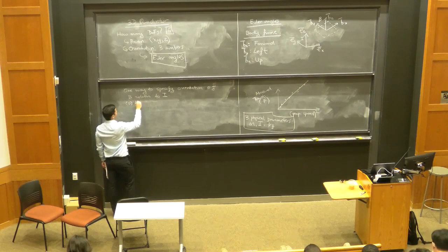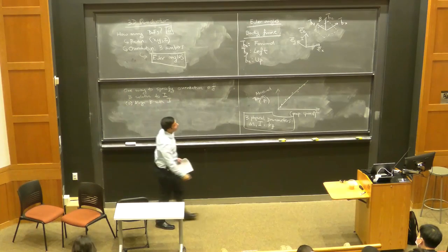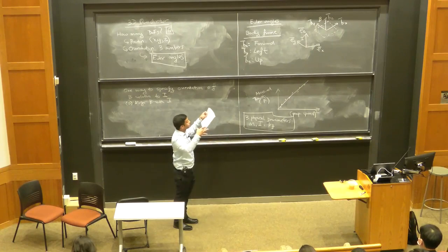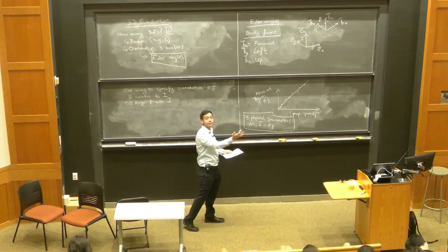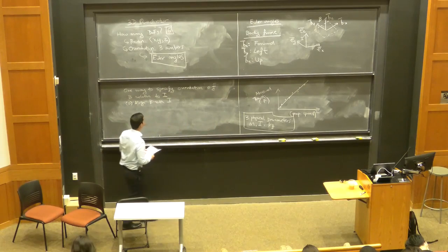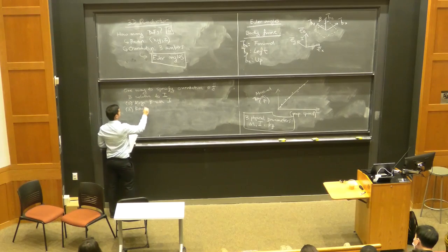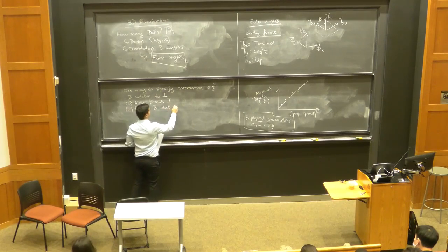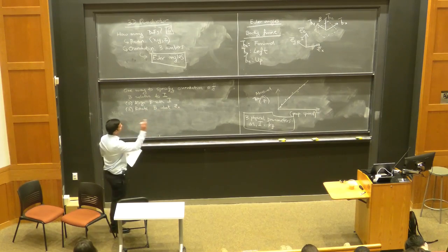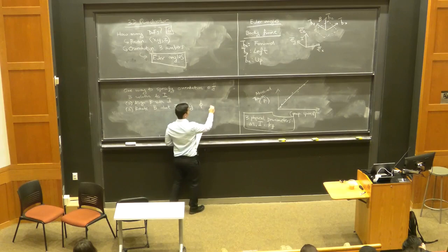And we're going to describe this process where we first start off, maybe step 0, by aligning B with I. So the 3 body directions, BX, BY, BZ. Just imagine that you start off by placing the drone such that the BX direction is aligned with EX, BY is aligned with EY, and BZ is aligned with EZ. The first step is then going to be to rotate the B frame about the direction EX, so about the inertial x direction, by some angle, which I'm going to call phi. And we're going to give this angle a name, the roll angle.